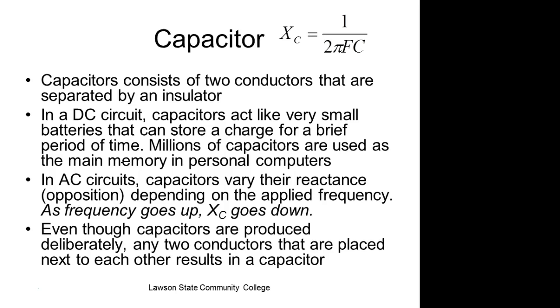So with capacitance, what happens on capacitors, as frequency goes up, their opposition goes down. So capacitors won't pass DC. They'll block DC because DC has a frequency component of what? 0. So true DC. If DC is varying, it will let the variation pass through, but it won't let the DC itself. But it creates a phase shift, and it drops a voltage without producing power.